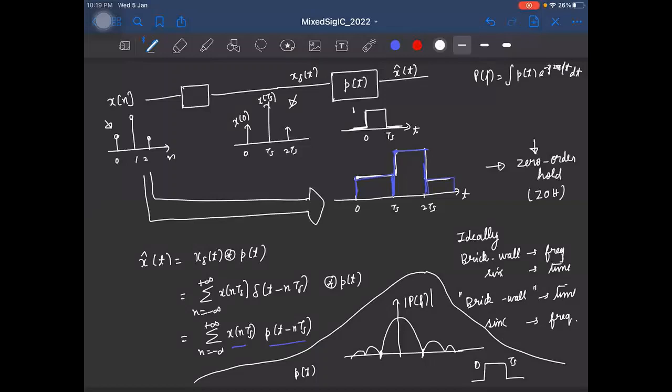So if you multiply a sinusoid with this pulse, we will have only the sinusoid existing for a period of Ts, right? From 0 to Ts. And if the Fourier transform is 0 at these points, what does it mean? The integral is 0. So essentially, the integral of a sinusoid from 0 to Ts is 0. What sinusoids can satisfy this condition? Only sinusoids that have one complete period in Ts, right? So the first frequency is fs, and the second is 2fs, right? Even if I have two periods within one Ts, this will be 0. So this is 2fs and so on.